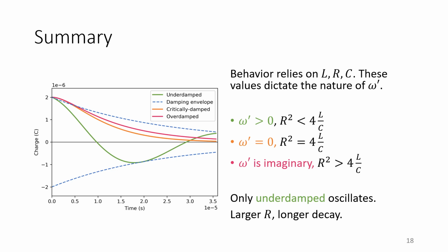So it's actually advisable for you, when understanding LRC circuits for the first time, to check the graph more than the solutions themselves. Now, you could also see here that the effect of R in your graph is that when you have a low value of R, the changes in your currents or the changes in your charges in the capacitor as well in the system will be much more pronounced. But if the value of your resistance is high, it will take a longer time for these values of charges to actually change.